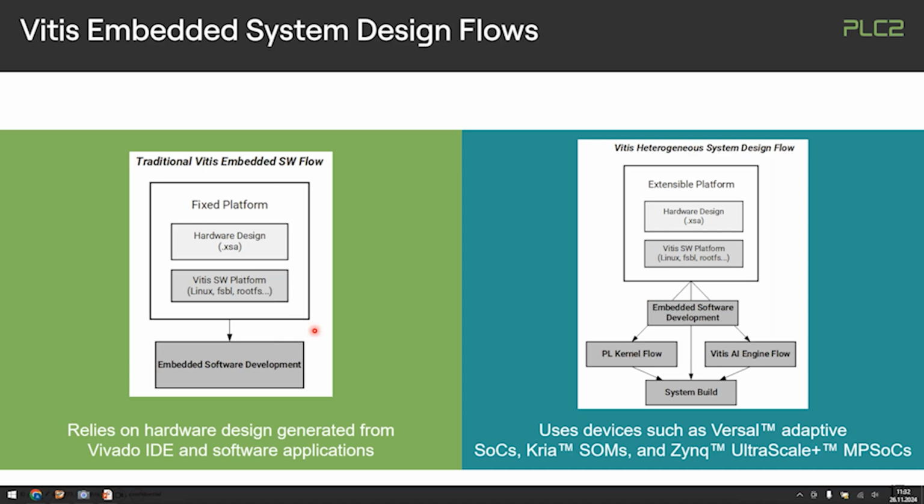So there is a concept called the extensible platform, where Vivado is doing as much as it can, or as much as you want it to do. Typically, you would go for the interfaces, the interconnects between PS and PL, and define that. But then within the PL part and within these new IPs, you kind of freeze this design in a half-baked way.